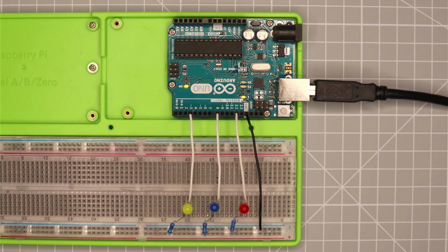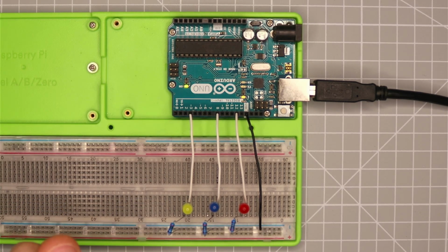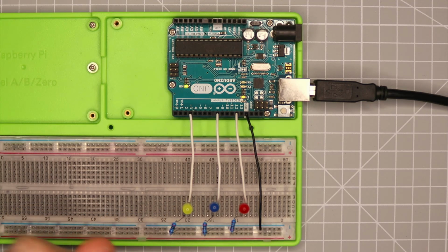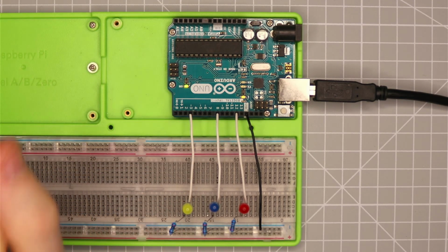And so what that means is that we're going to be sending down a message with multiple variables embedded within a single message. And what we're going to be doing is getting it to turn on and off these LEDs that we have here. For this setup, what I have is 3 LEDs, and each of the LEDs has an inline resistor, and I'll put up the circuit diagram in the section down below. We have pin 3, pin 8 and pin 12 controlling these 3 LEDs.